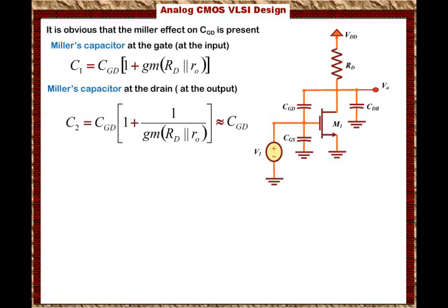So what we end up with is the poles are the same as the common source amplifier. And keep in mind that for the differential amplifier, what do we do when we use the half circuit symmetry? We say that this occurs for the first voltage, and the other circuit, which is identical to this one, will occur for the second input, right? Because there are two inputs, one at each end. Then you add up the two gains to give you the output voltage, which means that you will have the same response only added, right?